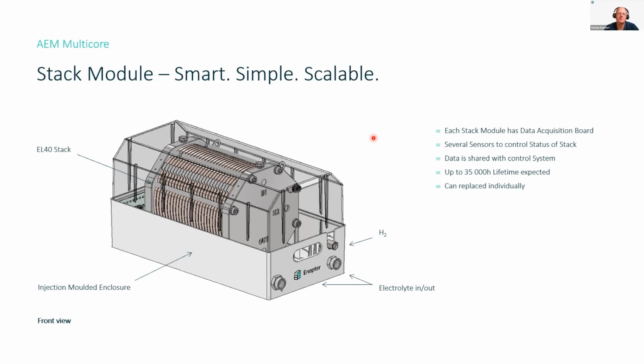Yeah. And perhaps it's important to reflect again that we have two options to regulate. So you have the production rate of the individual stack itself, or the string, 60 to 100%, and then you can decide how many strings you operate at a time. Correct. Okay, cool.